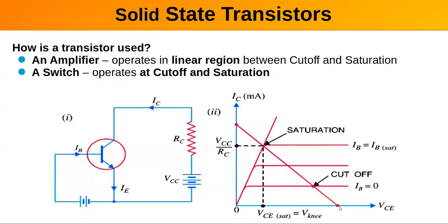So when it's off, whatever this voltage is what you're going to see on the collector. When it's totally on, you're going to see almost zero, but then you got some barrier junctions there, so it won't get to zero when it's in saturation.